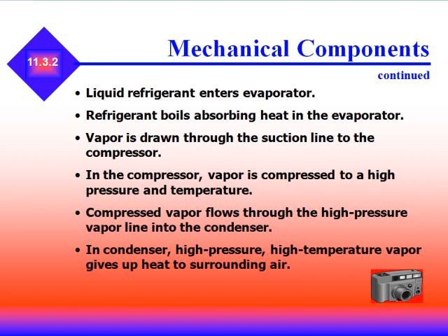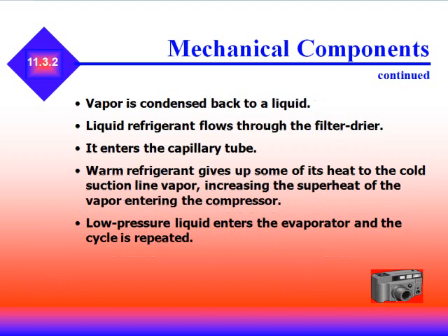Compressed vapor flows through the high pressure vapor lines into the condenser. In the condenser, high pressure, high temperature vapor gives up heat to the surrounding air.